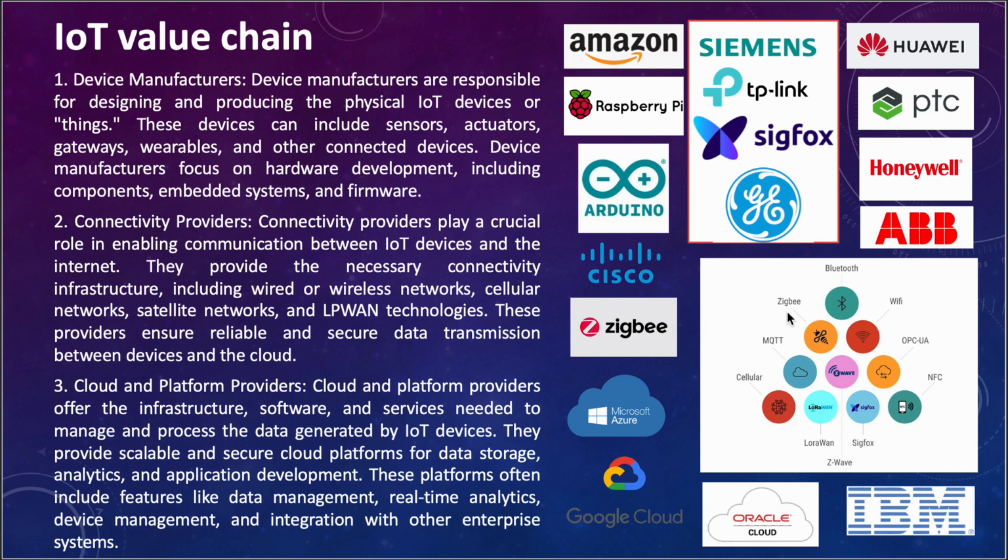You will see Zigbee, you will see Sigfox, LoRaWAN, Z-Wave is here. These networks are specifically dedicated to IoT networks. So sometimes when you have some kind of a sensor which is wirelessly fixed without a power source, or the power source is a small battery, and you need it to run for maybe a couple of months or a couple of years, you need networking protocols which will take less energy.